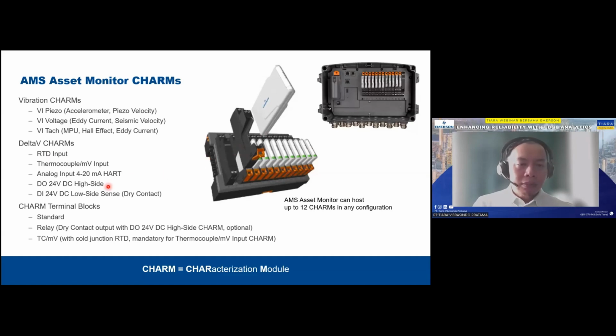We do have some requests. Can it be used as a protection? The answer is yes and no. Okay, yes. I will say yes, because we have this card as well that provides dry contact. So you can actually connect this to a tripping mechanism, your DCS, PLC, or your shutdown mechanism and so on, to make it as a protection, right?